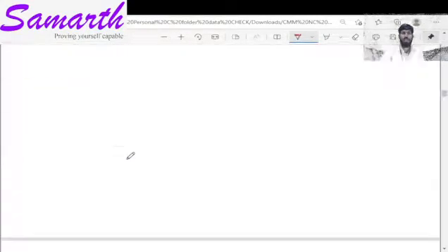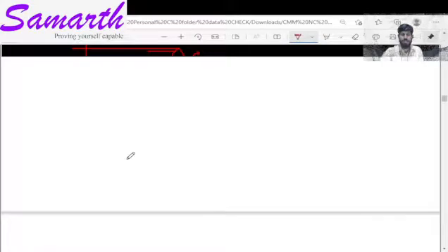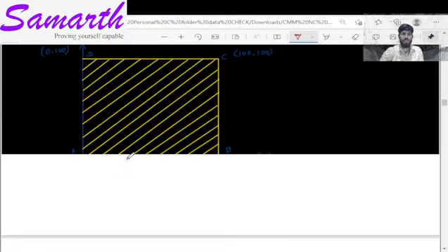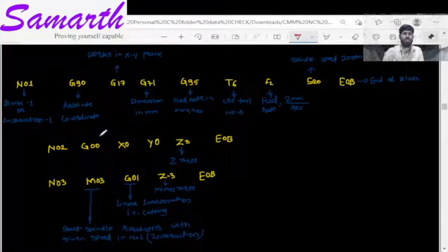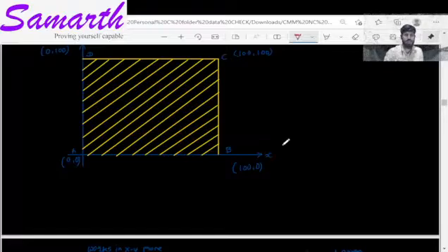After doing a particular operation or setting, if we want our tool to rapidly traverse to this position, let us say X0, Y0, Z3, then the tool will move to this position. Z3 means, let us say this is our component. We have already drawn.